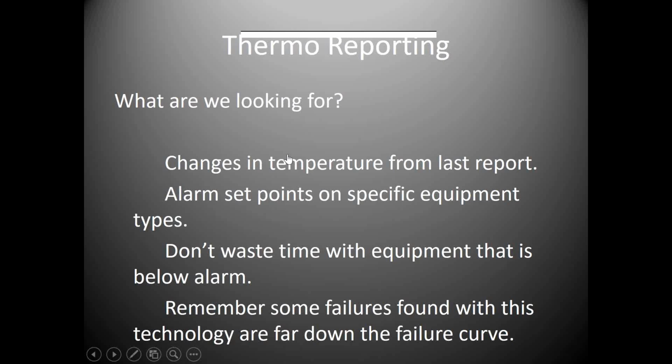I remember the very first thermographic report that the guy brought into me at the company. The binder was 3 inches thick, and there were like 200 pages in there. And I said, that's the last thing I want to see, 200 pages of issues, but some of the temperatures were only off 5 or 6 degrees. So I made it clear to the guy. I said, I want to see temperature ranges that are 20 or 25 degrees out of normal. And I want my report to be 1 inch thick instead of, 20 pages instead of 200. But I want to attack the big issues first.